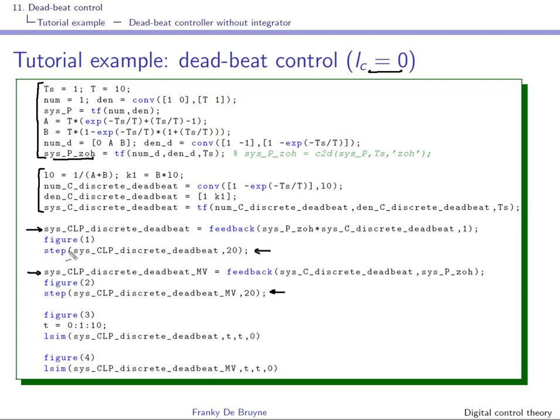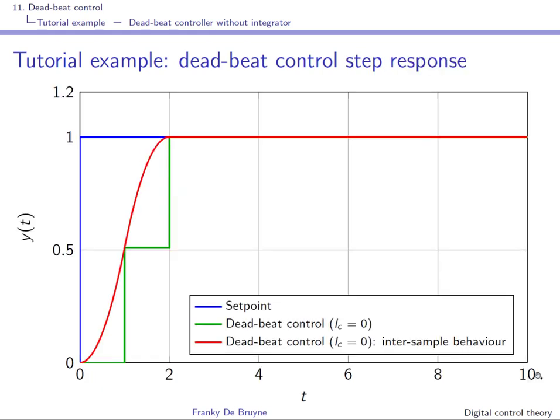Okay, so this is obtaining the output. This is obtaining the control energy, and this is new. We also obtain the ramp responses, and there is no command ramp. So what you have to do is use the command lsim, right? You could also use a step response and include an additional integrator in the process. That would work as well.